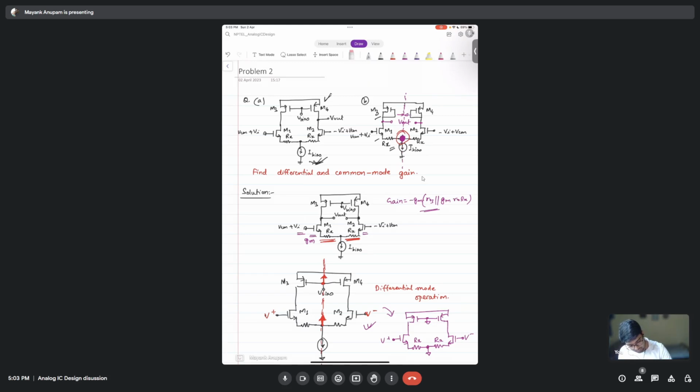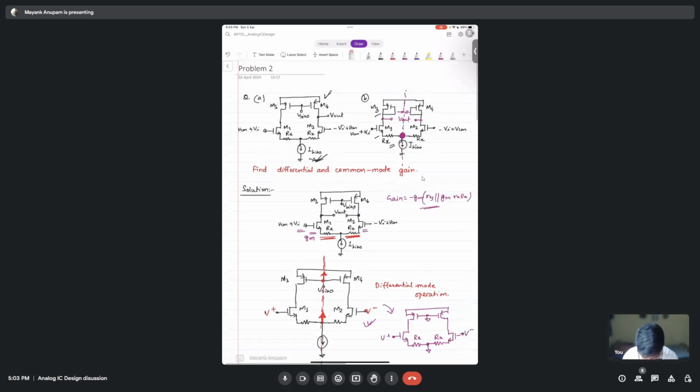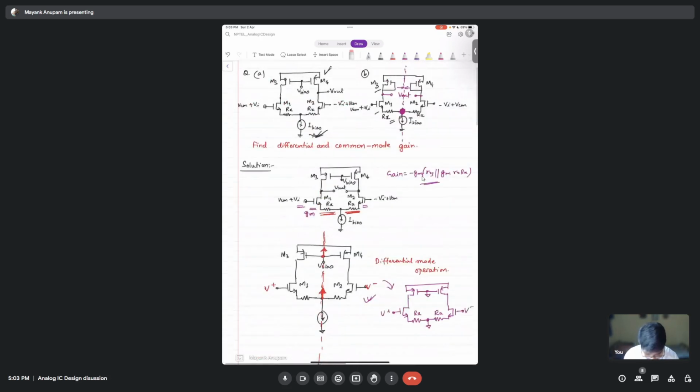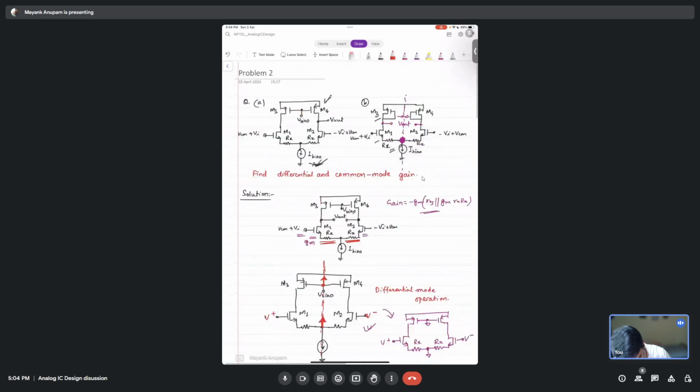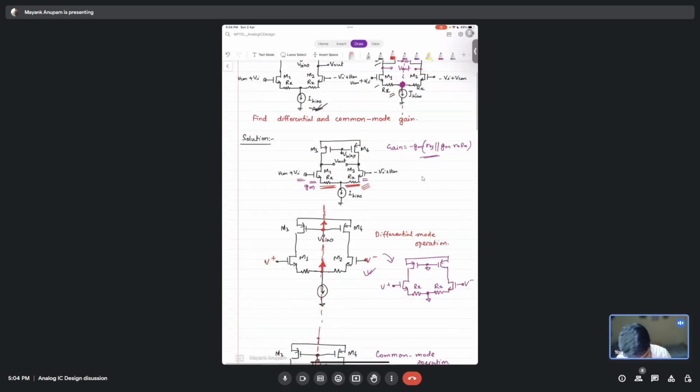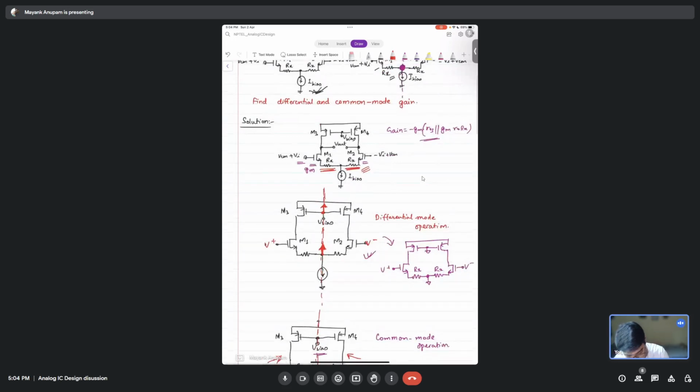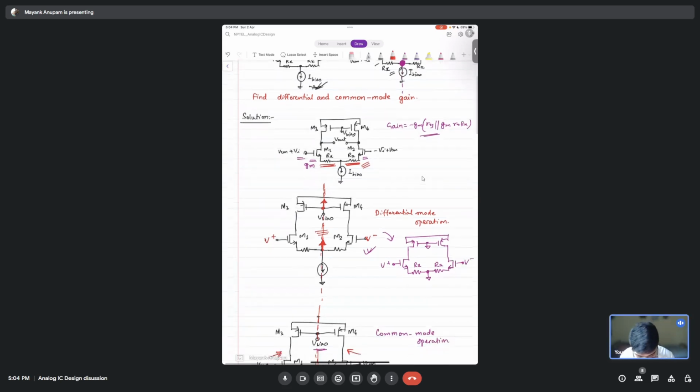I guess you are confused. Don't get confused. As I already talked about, in this circuit, this is the example that I told about. You see there is a mirror symmetry exactly in the half here. Anything which lies on that axis of mirror symmetry will become a short circuit, AC ground, for the differential mode operation. That is only true for differential mode operation.